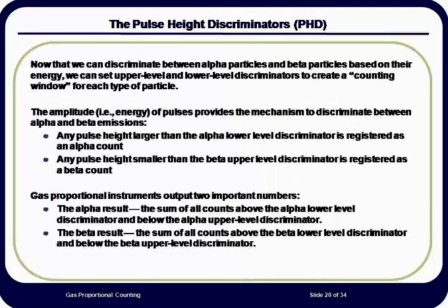Using the previous spectrum as an example, if we can use the detection system electronics to determine if a signal is either above or below a certain value of pulse height, we can distinguish between alpha and beta particles. This determination is done with electronic filters known as discriminators. The instrument will have both high and low discriminators for both alpha and beta energy regions. A beta low energy discriminator may be set in some instruments to reduce background noise from the instrument. An alpha high energy discriminator can be set at the highest channel in the spectrum, ensuring we record all the pulses from alpha particles detected.